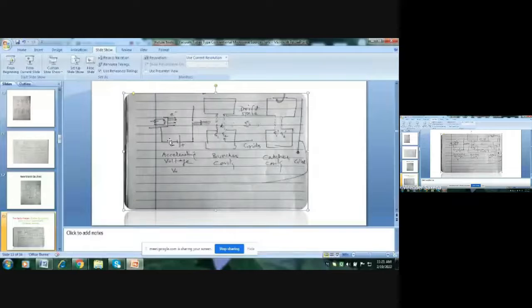So these electrons are uniformly accelerated by the DC field, meaning the velocity of all the electrons is equal. And when these electrons pass through this anode, we get a pencil-like beam of electrons which interacts with the cavity. So this is the first jerk which this cavity experiences from these charge carriers, and an RF field is generated inside the cavity.